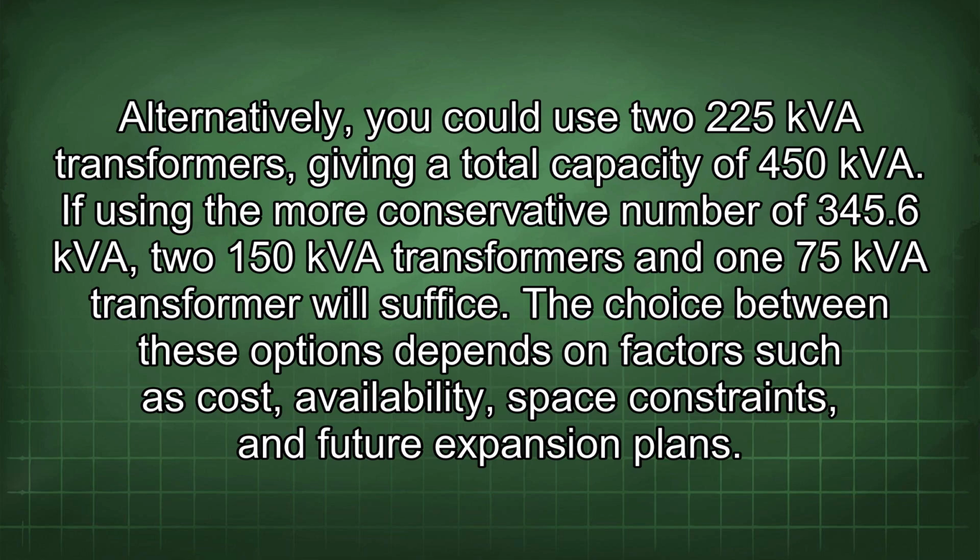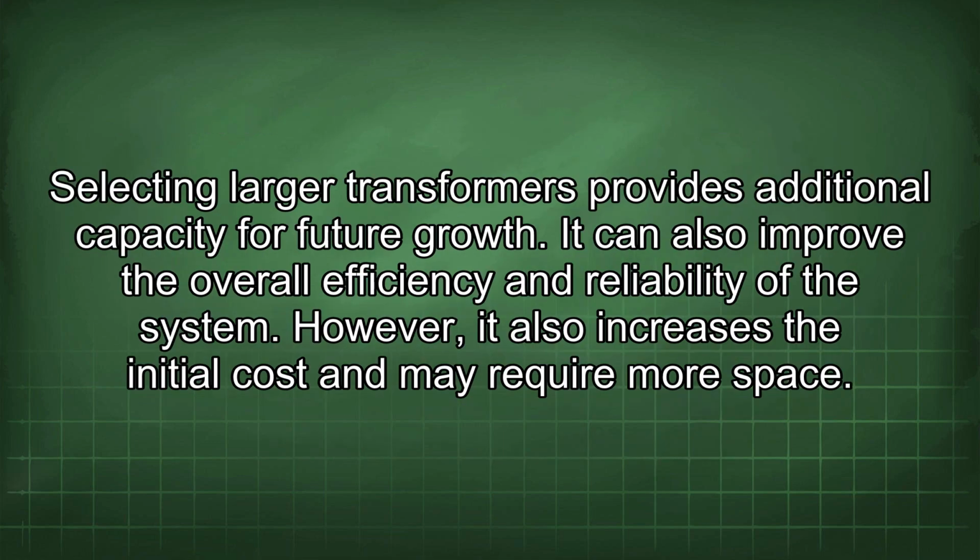The choice between these options depends on factors such as cost, availability, space constraints, and future expansion plans. Selecting larger transformers provides additional capacity for future growth. It can also improve the overall efficiency and reliability of the system. However, it also increases the initial cost and may require more space.